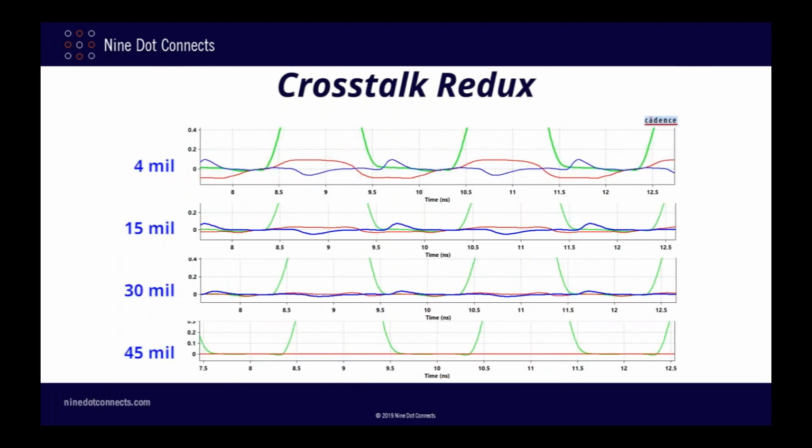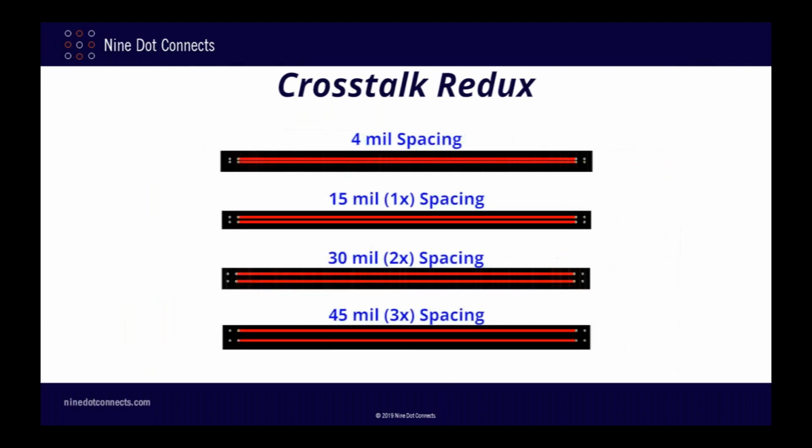And here are the time domain waveforms. I've chopped off the driver signal since we're just interested in the noise signal traces. As you see, they also follow the same trend, ending with no measurable noise for the 3x spacing scenario. I think these design cases were a good demonstration of both the effects of crosstalk noise and the means of mitigating these effects by increasing the intra-trace spacing.